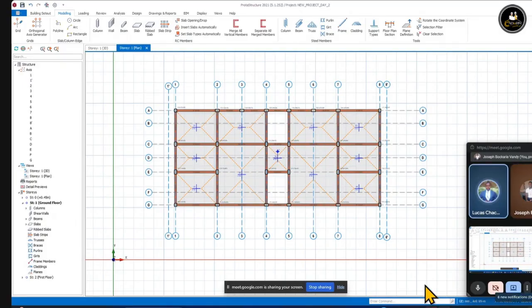So we have areas with zero bending moments, especially at the edge of the beams. So the software will always assume all points as fixed points, or as fixed connections, but we have some hinged joints, we have some pinned.